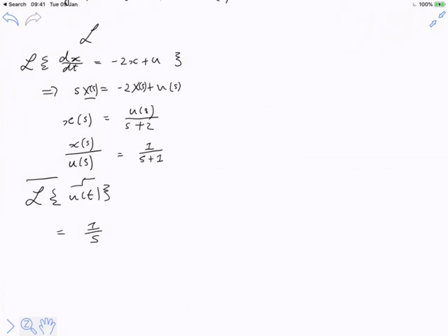And so the things that you expect from Laplace transforms, functionally, right? Being able to calculate the Laplace transform of a system described by differential equations, that's going to be exactly equivalent to calculating the Z transform of a system described by difference equations. Okay? And being able to calculate the Laplace transform of a function of time like this, a signal, that's going to be exactly equivalent to calculating the Z transform of a sampled signal of time in the discrete domain. So all of the things that we have over there, we're going to be able to do for the Z transform. Or we're hoping that that's where we're going to end up, right?